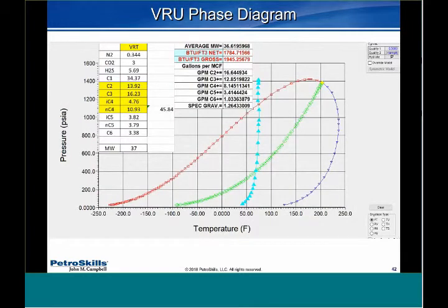You can see the temperatures are much lower. This is the gas that's going to come off the vapor cover system. Okay, and if you look at it, 45% of it is ethane to butane. Also, the molecular weight of the gas is really high. It's heavier than air. So if this is coming out of your tanks, the thief hatches are open, it's going to fall to grade, and the heating value is like rocket fuel.